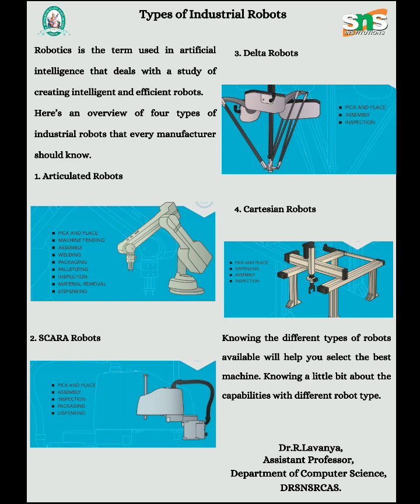It is the type of robot that comes to mind when some people think about robots. Much like CNC mills, articulate robots are classified by the number of points of rotation or axes they have. The most common is the 6-axis articulate robot. There are also 4 and 7-axis units on the market. The flexibility, dexterity, and reach make articulate robots ideally suited for tasks that span non-parallel planes, such as machine tending.